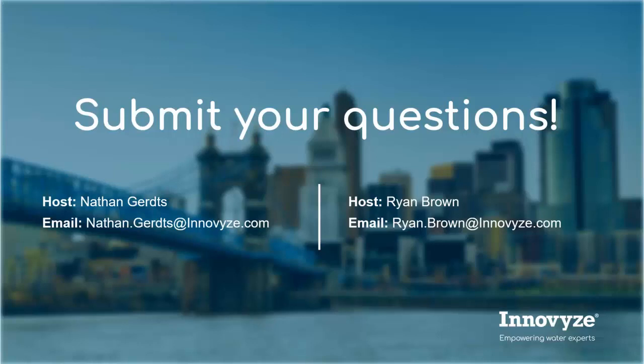It might be. I don't know if you're talking about mesh manipulation or being able to do some of the things you might be able to do within ArcGIS, like cutting out certain parts of a model. The closest thing that we would have to any kind of mesh manipulation would be mesh level zones, where you can specify, like if you wanted to grade in a ditch or something like that, you could use a mesh level zone to achieve that.